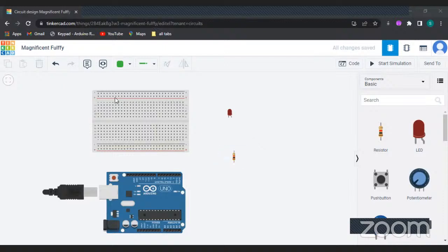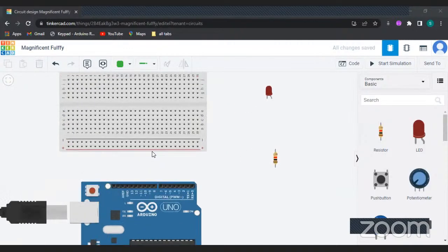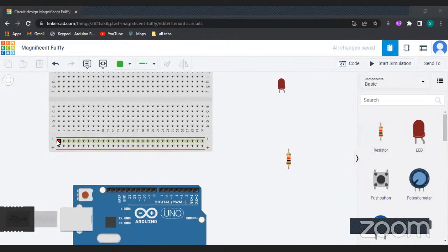Okay, so now I've deleted the two wire components. Now I want to make good use of the down part of the breadboard. So what am I going to do? Good, this is the ground or the GND. You click on it. Don't forget, your wire type is already set to normal. So just click on it and bring it down here.